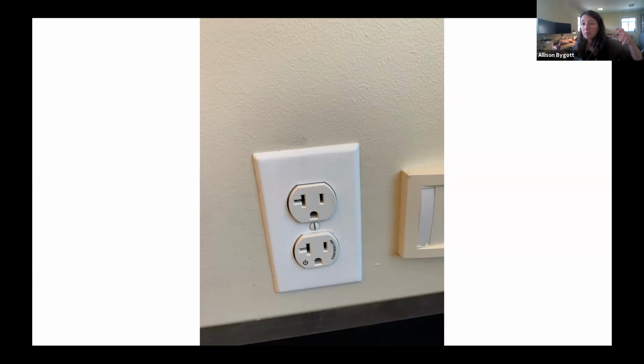They're thinking about, can they plug the wiring in instead of having to bend the wires around the screws that are the terminals on the receptacle. They needed some of the receptacles to be GFI protected. It was hard to work out this controlled receptacle piece. So you might need to think about it if you have different situations, and even work with your electrical contractor.